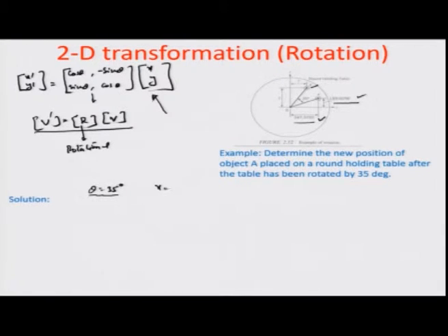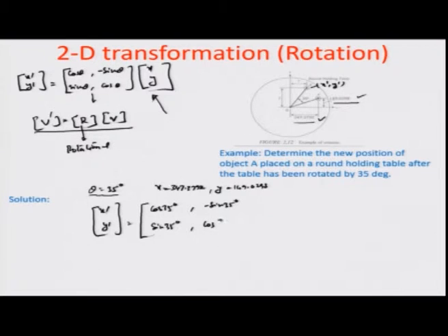The coordinates x and y are represented again by two rather long numbers, 347.3792 and 149.0298. Intentionally it has been made so that you have to use the matrix transformation, otherwise it becomes a little complex. So, when we talk about finding out what are the location coordinates of x dash y dash, which is the point A dash in space after the rotation has been executed, the matrix x dash y dash comes out to be equal to cos of 35 degrees, minus sine of 35 degrees, sine of 35 degrees, cos of 35 degrees, times these two x and y